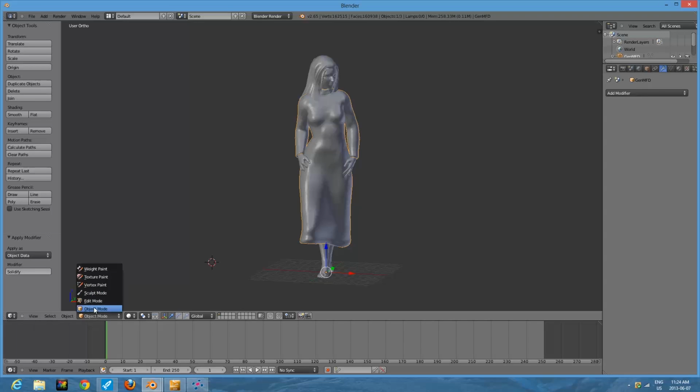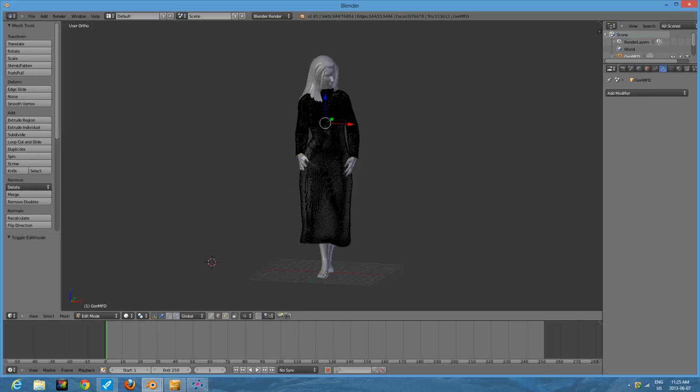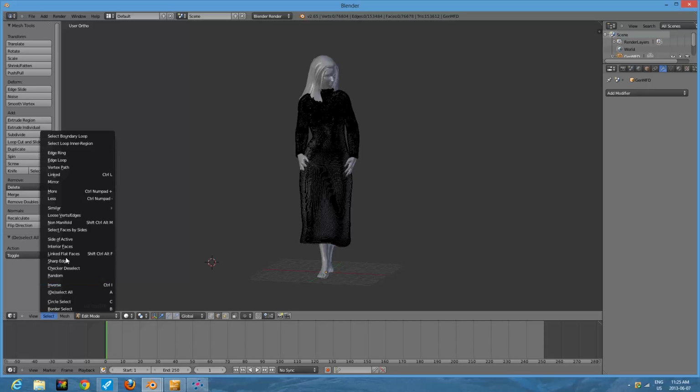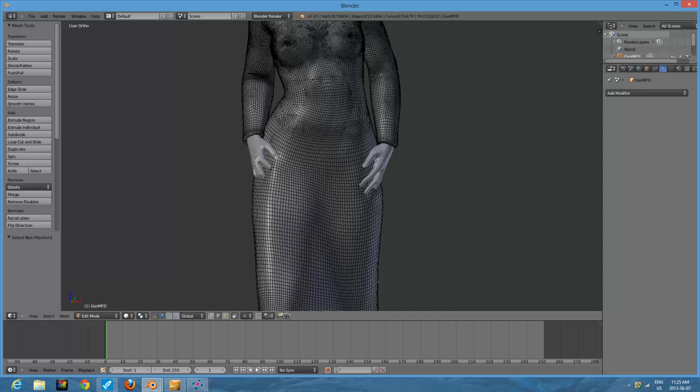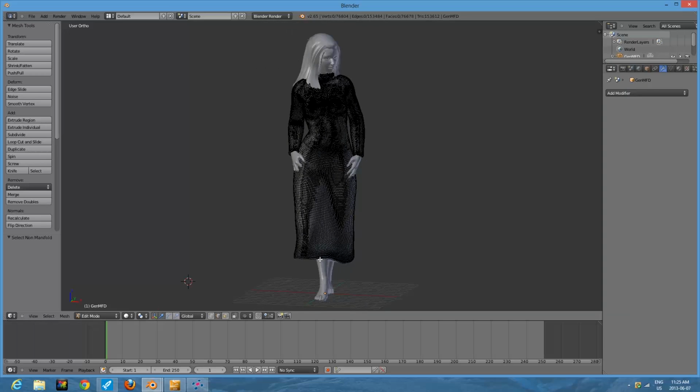Okay, now let's take a look at that in edit mode. Okay, you can still see that selected there, those orange, because that was saved from last time, so just unselect. Now let's hit non-manifold again. You'll notice it's not highlighting this time. That's because when I thickened it, it actually took care of the manifold problem. But if you didn't want to thicken the dress, you could have just gone to the sleeve and done the same thing I did at the base of the dress in this case. It's a very simple dress.